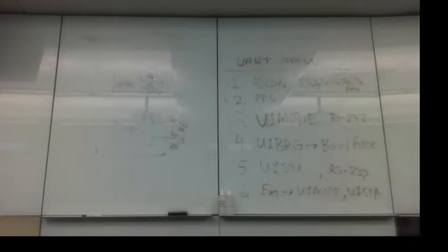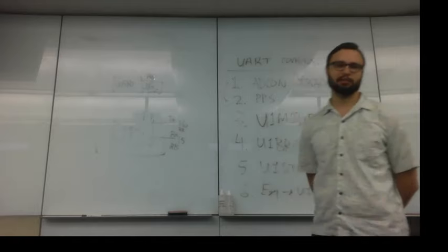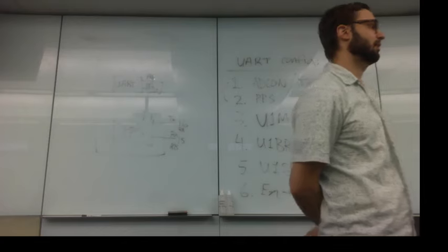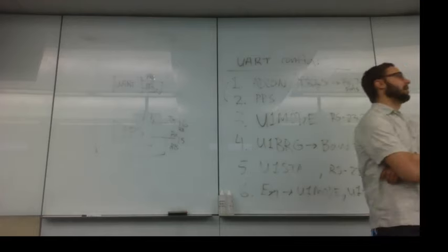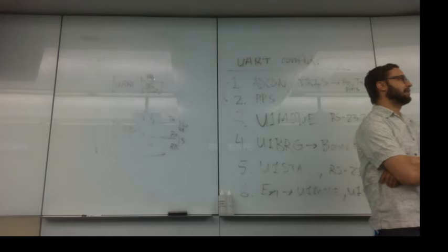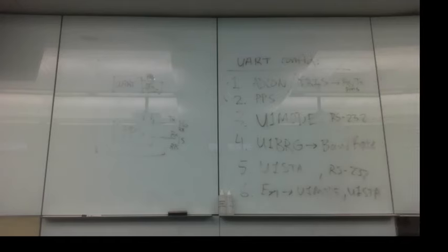These days, there's chips that do RS-232 over USB, so you don't really have to know much about either one. But basically, it was developed as a common interface in the 1960s, and it was designed for connecting a terminal to a mainframe server.